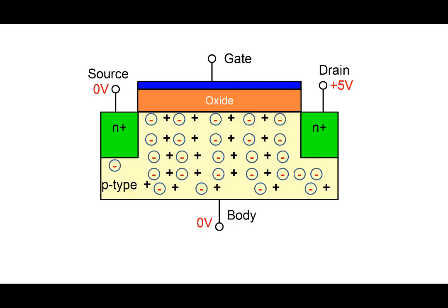But then things become interesting. Things become interesting when you apply voltage to the gate here. So I've drawn a P-type semiconductor here. P-type semiconductor will have all these ionized acceptor atoms here, encircled minus sign there. And plus sign denotes all the holes that are there. Again, the acceptor atoms are immobile. The holes are, of course, they can move around. And so there are a lot of holes here, and maybe very few electrons. So one is shown, maybe 1 electron here.